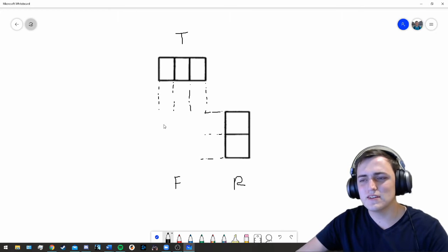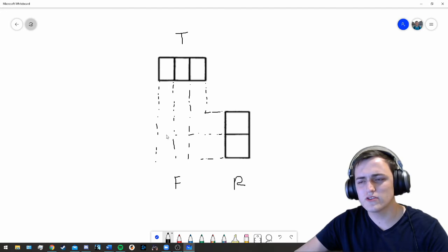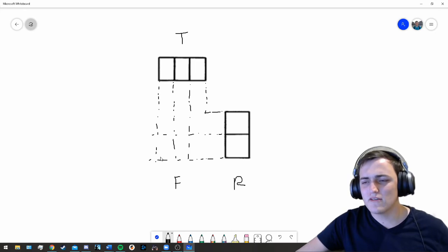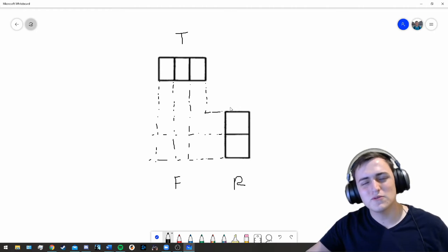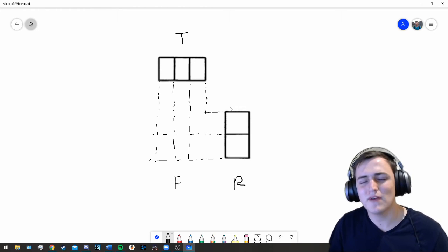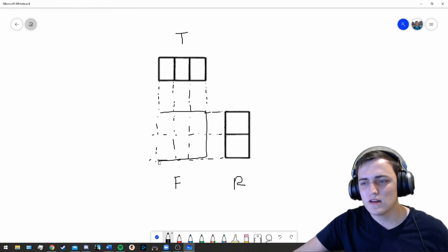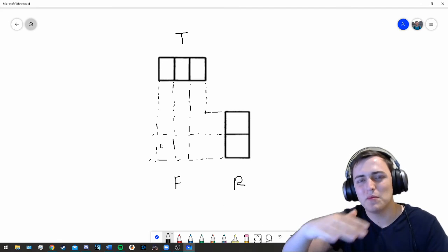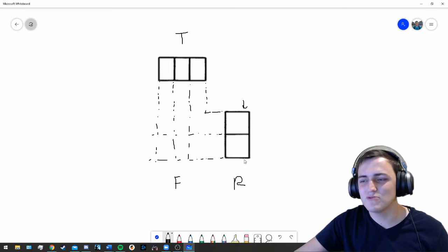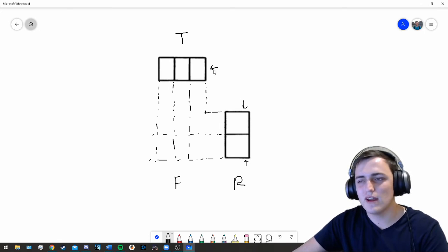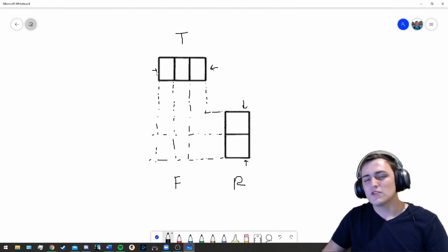And so now we see we've got these instruction lines. How do we know where to place our object lines? Well, we know we're going to have a full width part in both views. We're going to touch the top and bottom and the left and right bounds of that full square, right? We've just drawn a rectangle here. Our shape is not a full rectangle, but we know that we're going to touch those left and right and top and bottom bounds just from seeing that there's an object line at the top and bottom and the left and right in the top view. We know we're going to be tracing those lines down somewhere.